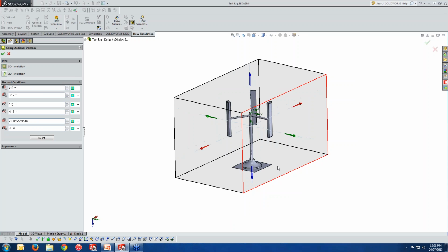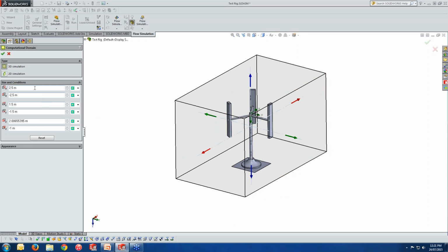One other good thing you can do, in any of the XYZ directions, is say there is a symmetry, meaning exactly the same model is repeated in the X plus direction. That is very good since you might use a symmetry in your simulation and would like to reduce the calculation time.